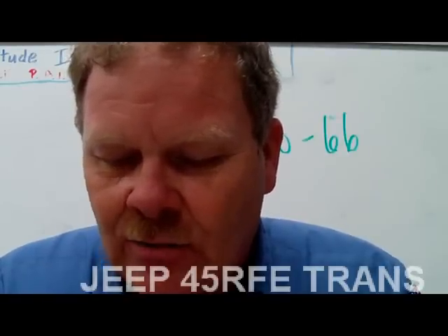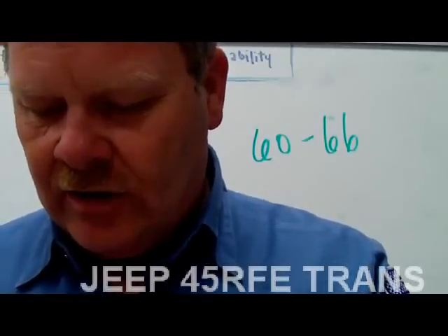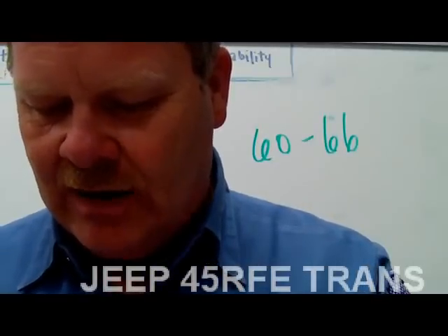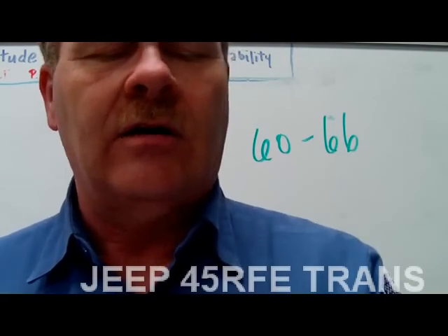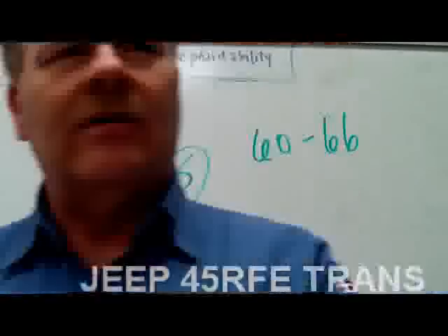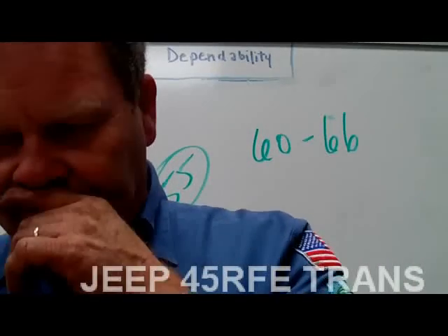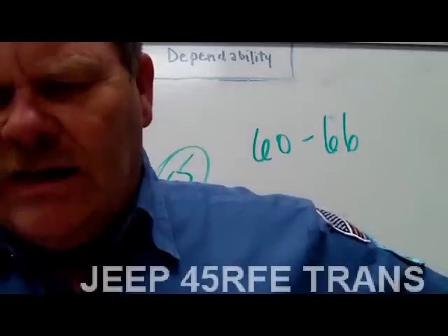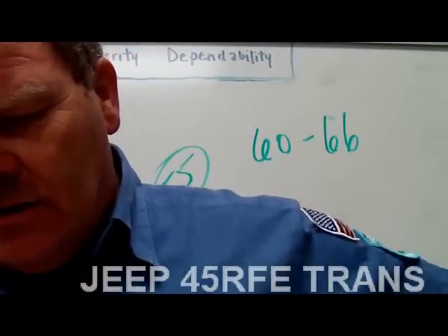It's got some features that really set it apart from other transmissions. It's really unusual. The torque converter has got needle-type thrust bearings instead of, like the one that we took apart in here, which just has kind of fiber thrust bearings in it. Of course, there is a needle bearing on the stator on that one. It's got a dual-stage fluid pump. It's got 3 gears, 1 drive gear and 2 driven gears.